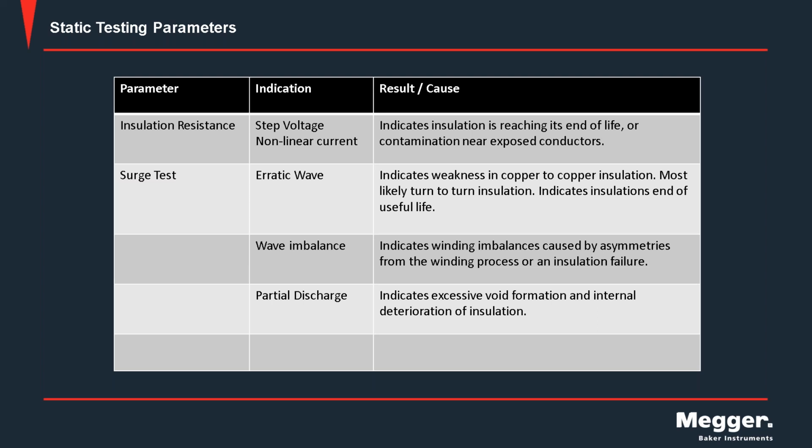So we evaluate that for the wave stability. We evaluate the balance of the waveforms in some cases, specifically when the rotor is removed. And then we can also use the surge test to evaluate partial discharge. So we have a tester, the DX tester, for example, that will look at the surge wave and identify high frequency content that's associated with partial discharge.